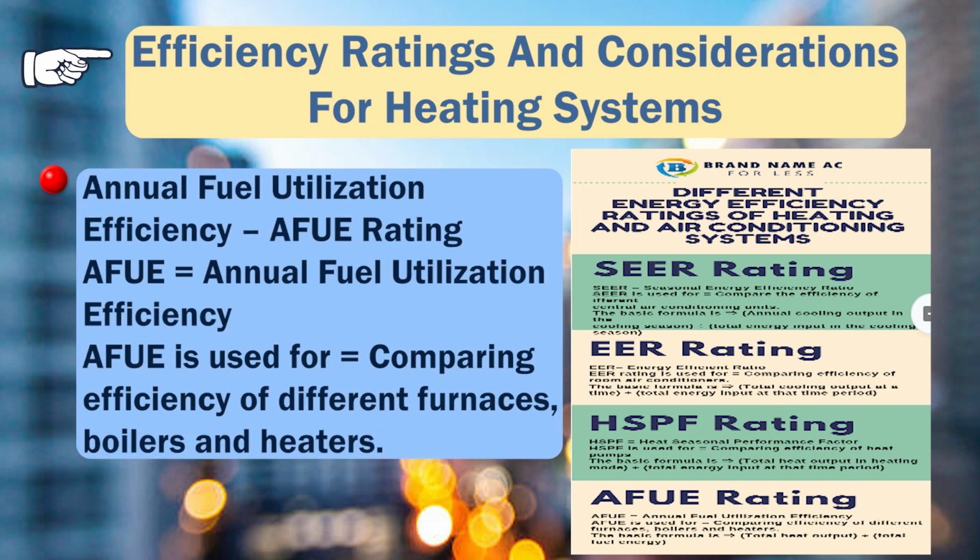Next is AFUE, annual fuel utilization efficiency for furnaces and boilers. This percentage indicates how efficiently a system converts fuel into usable heat. A high AFUE rating signifies better efficiency. Example, a 95% AFUE furnace uses 95% of the fuel for heating and loses only 5% to exhaust.